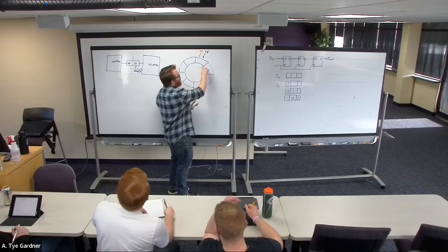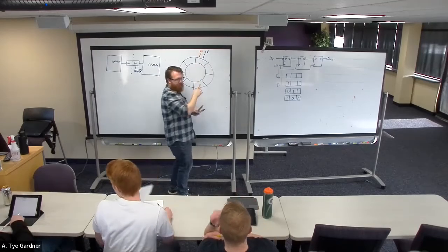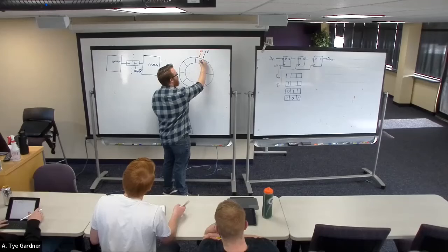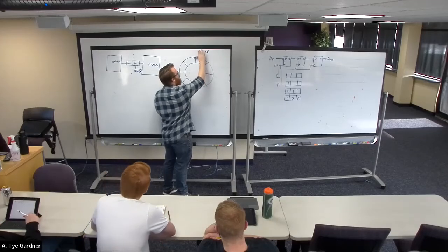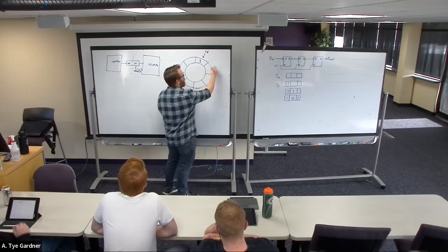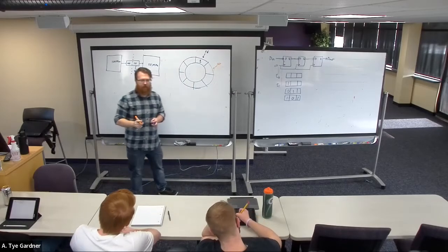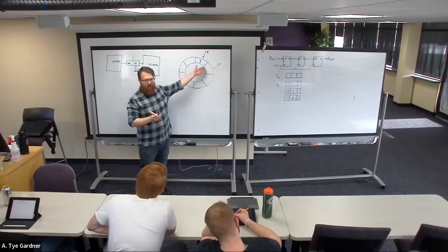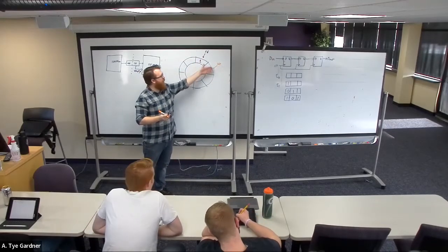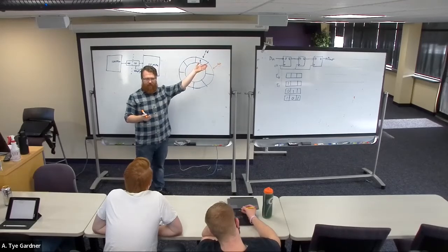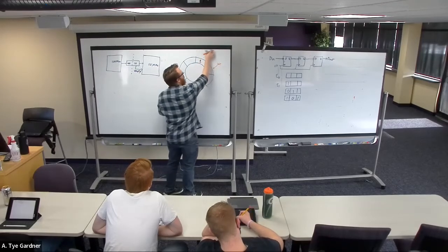Then if I write a value, let's say I store a 1 in here, the write index will update. Now we're not empty. There's a 1 here. If I read, the read index will update. This 1 will stay there, but the empty signal arises. So we read.